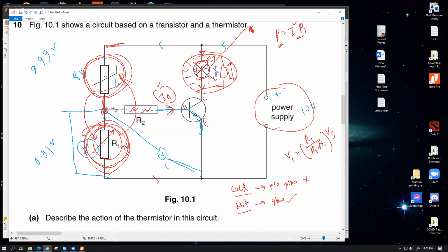So you can fine tune the performance of this whole thing by controlling the resistance of this thing, so that you can essentially fix up the exact temperature for which this will work. So this is another aspect. So I have talked about a couple of things. First of all, we can use the same device for both types of warning, too hot or too cold, by swapping out these two pieces. The second thing that I have told you is that we can fine tune exactly at which temperature this will blow up by controlling this resistance value over here, so that we can have the sharing measured and activated through the base current for a very specific temperature range or for a specific temperature value.